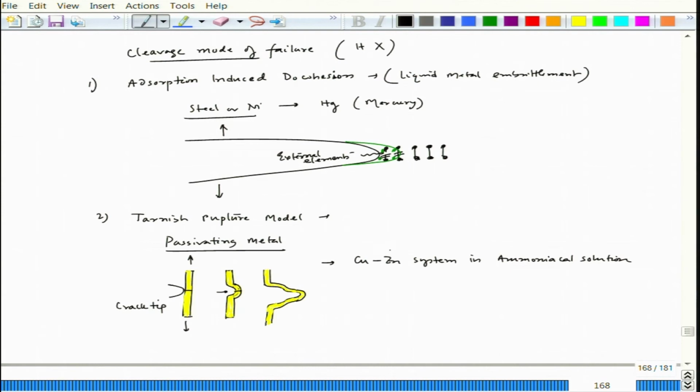So, this kind of SCC is observed, and this is the typical SCC. For example, if you recall, we talked about season cracking of brass casing of bullets early, what used to happen in the early 1900s. That has been solved by removing residual stress at the crimp portion, but how it grows can be explained through this.